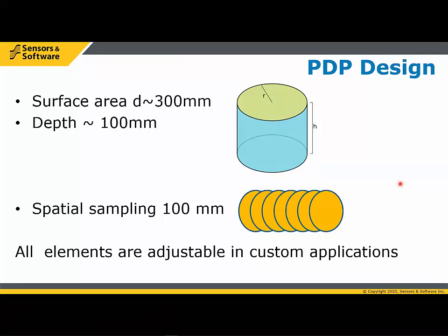So if I were doing a lane right now, I don't think that 3 units mounted on a vehicle would adequately sample a whole lane. With the footprints we have right now, I think you want to have 6 or 7 units across the lane to get adequate full lane coverage. I think there was a second question to that about making maps out of multiple lines of data.